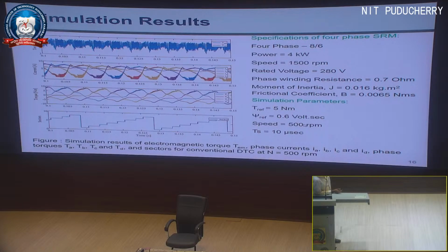So you can see in the third one, the torque is below 0, so negative torque is produced, which is what we try to address. We don't want negative torque. And in the second waveform, even though for example the orange torque is 0, you can see that correspondingly in the current waveform some small amount of current is drawn from the supply, which we are also trying to address. Because when no torque is produced, why is the motor still drawing current?